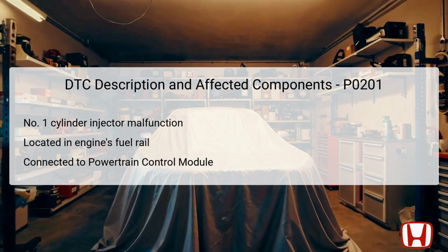The PCM and the injector are connected via wires that need to be checked for continuity, shorts, or breaks during the troubleshooting process.